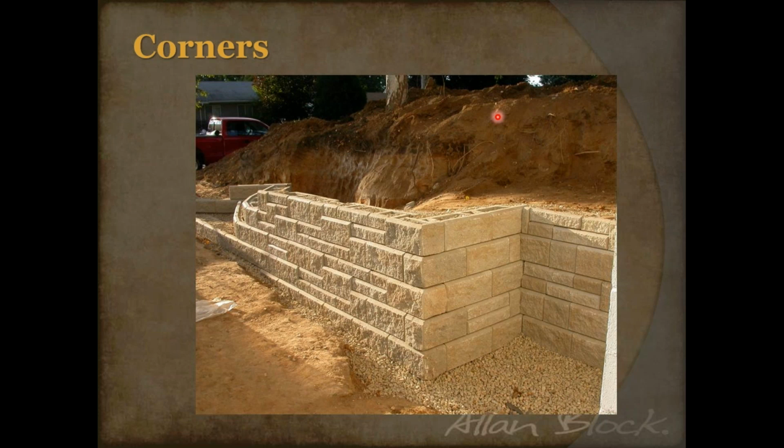And so try to make your corners look outstanding. You can make that cut, maybe go 2 or 3 feet back, being the meat of the wall, and that way the cut isn't right next to the corner. And I guarantee you're going to be happier with the result. It's just a way to raise the bar, increase your professionalism, make it look outstanding. That cut, hardly anybody will ever notice if it's in the wall, as long as it's not in that corner. And like I said, you're going to be making that cut if you got multiple corners that you're working with.